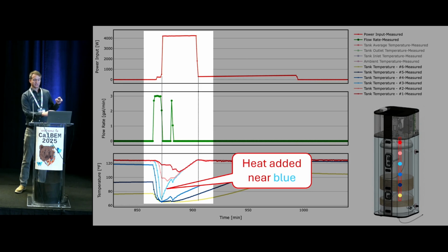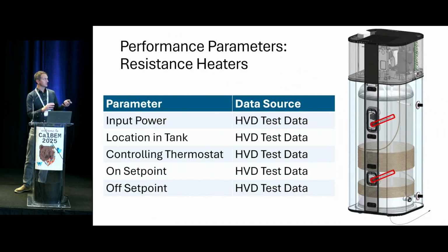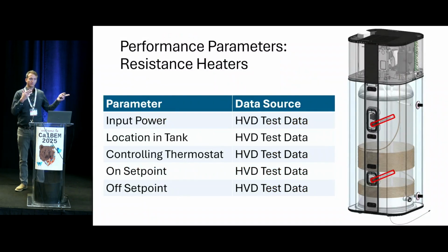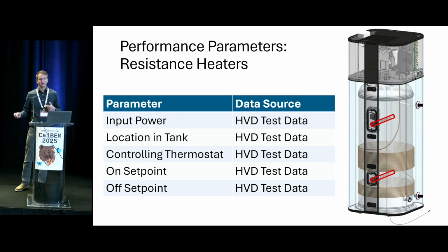And that gives us all the information that we need to determine the performance under any situation for when these resistance heaters are going to kick in. It's pretty rare, actually, that the lower thermostat or the lower resistance heater is going to kick on. That's kind of a last-ditch effort if the entire tank is depleted. So that's the resistance heat.